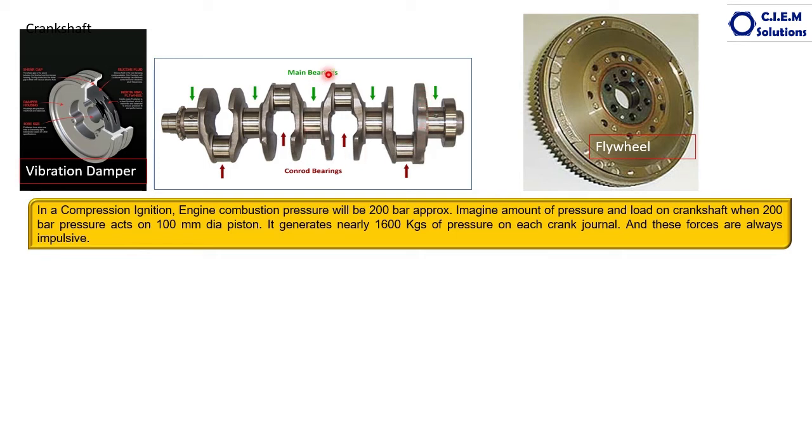The shaft is rotating. It generates a lot of centrifugal forces. Okay, these centrifugal forces tend to make the crankshaft bend or even break. To absorb all these centrifugal forces, these crank webs are provided. In the larger capacity crankshaft, separate bolt-on crank webs are provided, and these crank webs are dynamically balanced along with the crankshaft.